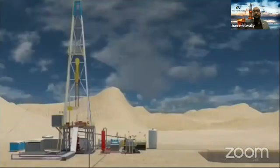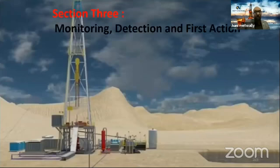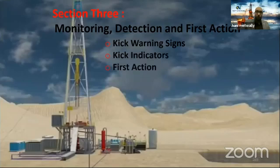Now we are familiar with the most common reasons of a kick. So the second or third section will be how to monitor, to detect, and what is the first action we need to take if we have a kick. We will discuss in this section the kick warning sign. What is the meaning of kick warning sign? Kick indicators. What is the first action we need to take? How we can shut in the well. How we can control the well if we have a kick.